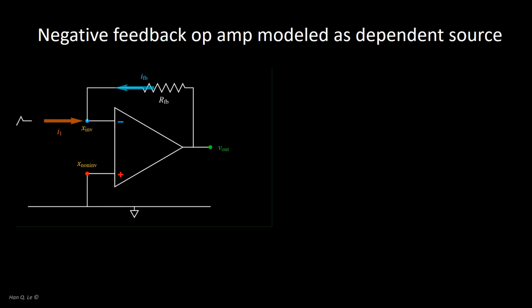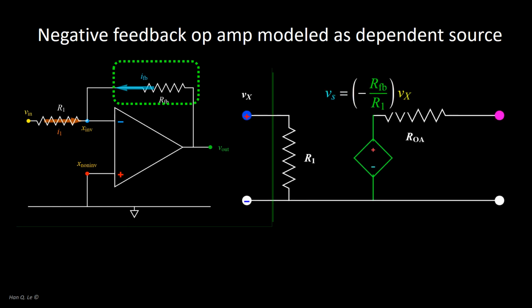This Lab 4 assignment is about the op-amp model with negative current feedback IFB, via resistor RFB. As discussed in Part 1, Step 1.3, given the infinite open-loop gain approximation, the op-amp circuit acts like a simple voltage amplifier where the output, Vs, is linearly proportional to the input Vx by a constant factor that is the ratio of two resistances, the feedback and the input.